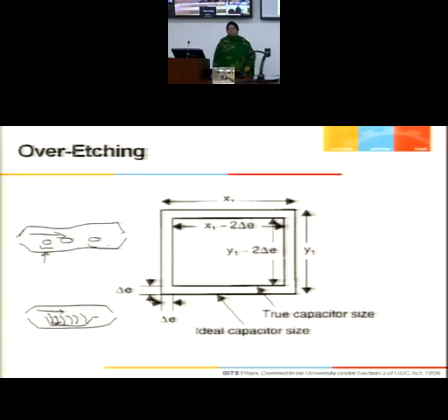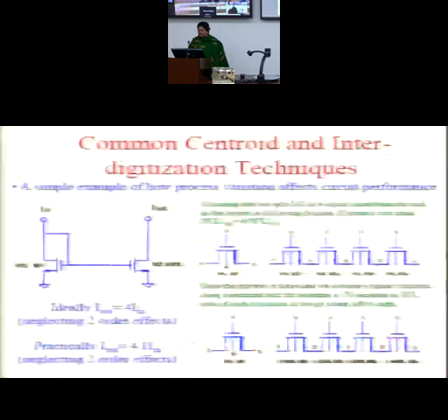So now if you go for matching, think of a matching. I have two MOSFETs in a differential pair arrangement or in a current mirror arrangement where I need a matching between these two. So what I do, I make each transistor by using multiple fingers. And then what should I do to create similar boundary condition effects? So what do we do actually? Understand that? Let me take a blank slide so that I can draw on that.